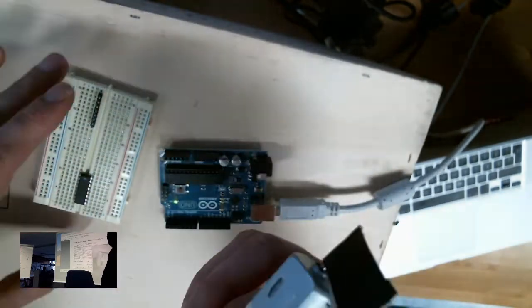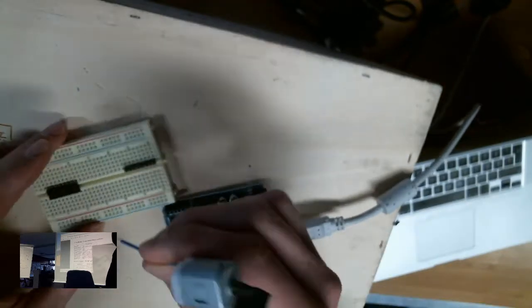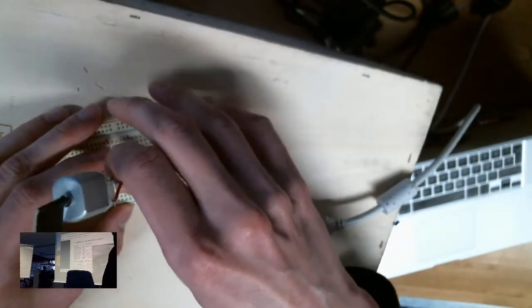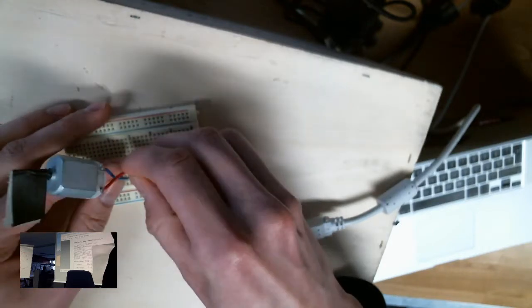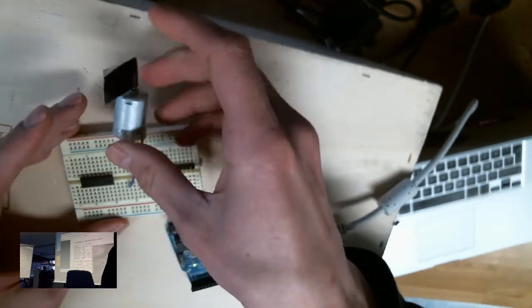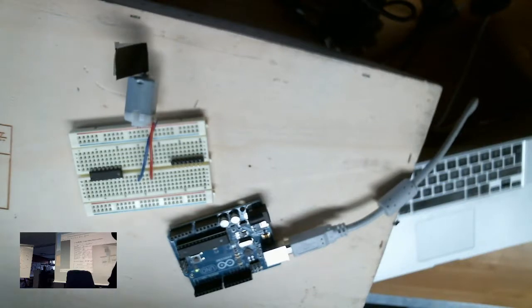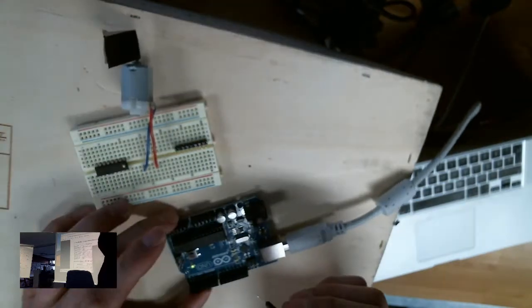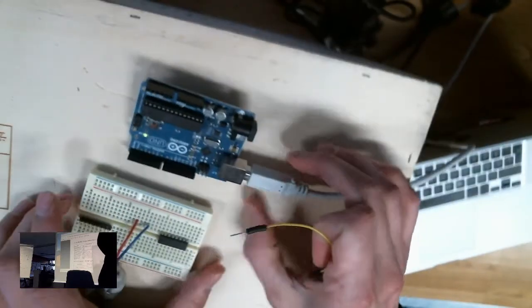But our intention is actually to be able to control that. In order to do so, we're going to connect the motor first to the breadboard, like so. I'm going to insert the blue cable here and the red cable here. And I'm going to use a few jumper cables in order to connect them to two different digital pins on the Arduino this time.